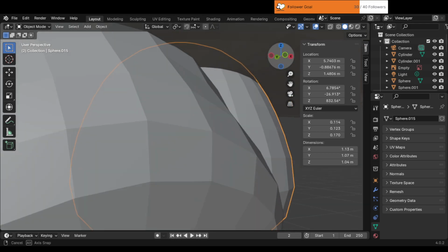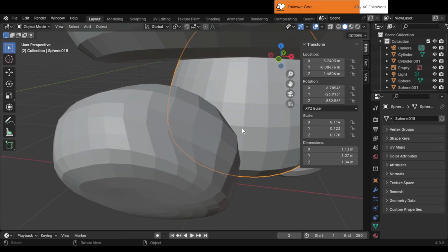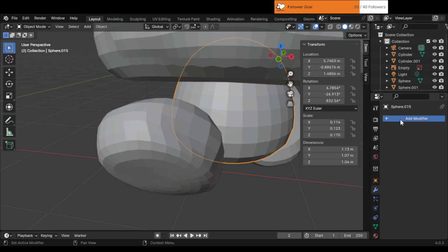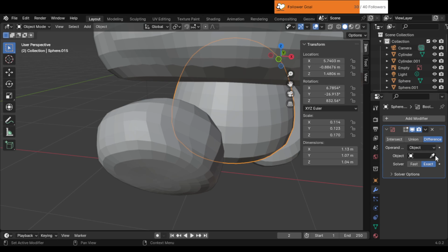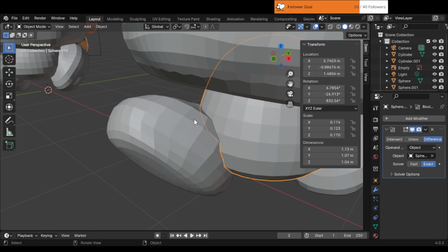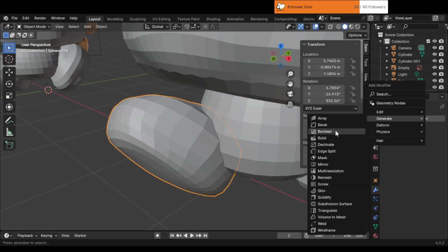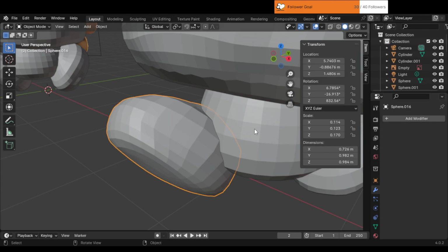1. Prepare the meshes. Inspect and clean up. Check mesh integrity. Make sure there are no non-manifold geometry issues such as self-intersections, holes, or duplicate faces. Resolve issues. Use the Mesh Cleanup menu in Edit mode to eliminate double vertices, fill holes, and fix other issues. Apply transformations. Reset transformations. Apply all transforms. Control-A all transforms on each model to ensure consistent scaling, rotation, and location.